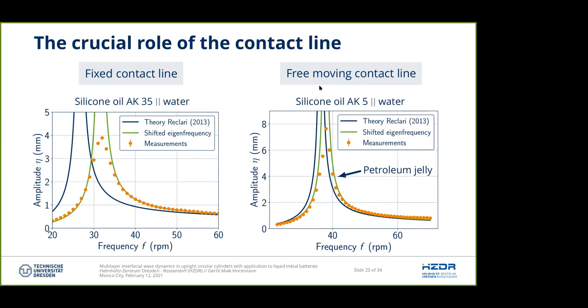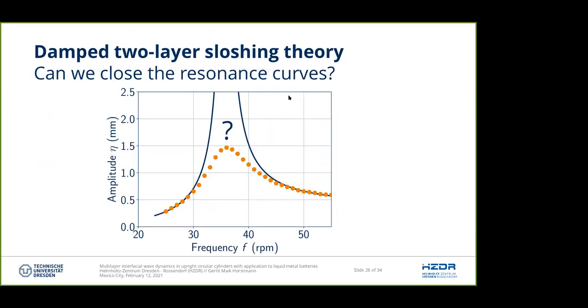So usually I had either fixed contact lines or some contact line hysteresis, some even more complex dynamics where it was partially pinning, partially moving, so very complex, uncontrollable dynamics. So these results stress that we have to include these effects in future to describe the metal pad roll stability in small and mid-scale cylinders.